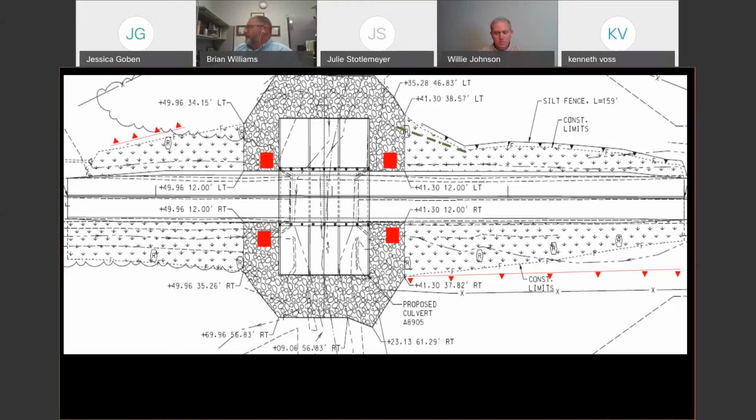You've got sediment traps in your existing ditches, because again, you're going to come out there, you're going to have to peel back some of that existing roadway. You're going to clear the grass. You need your additional silt fences out there. Based on what I'm seeing in the pictures, we ought to have protection on those perimeter control areas where water's leaving our job site. And then make sure we've got those outfalls protected. Okay.